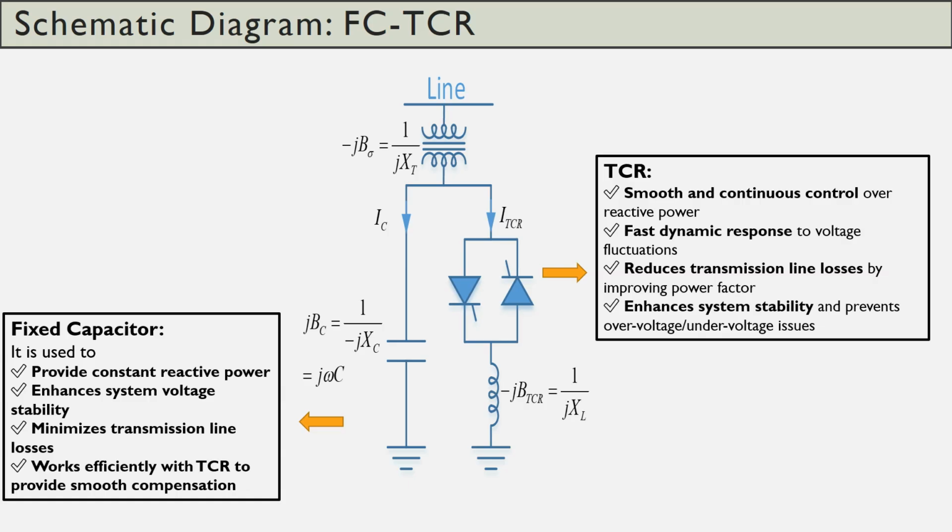Then it reduces the line losses. It improves the power factor. As the power factor is improved, the losses are reduced. It enhances the system stability and prevents overvoltages and undervoltages.